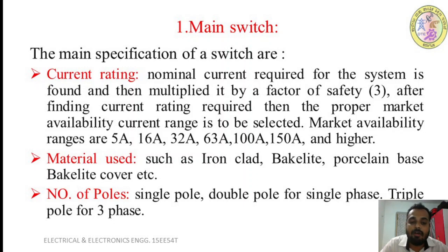Next, the materials used, such as ironclad, bakelite, porcelain-based bakelite cover, etc. These are market available, but normally we use ironclad switches. Next you have to see the number of poles. It may be single pole or double pole for single phase supply, and triple pole for 3-phase supply.